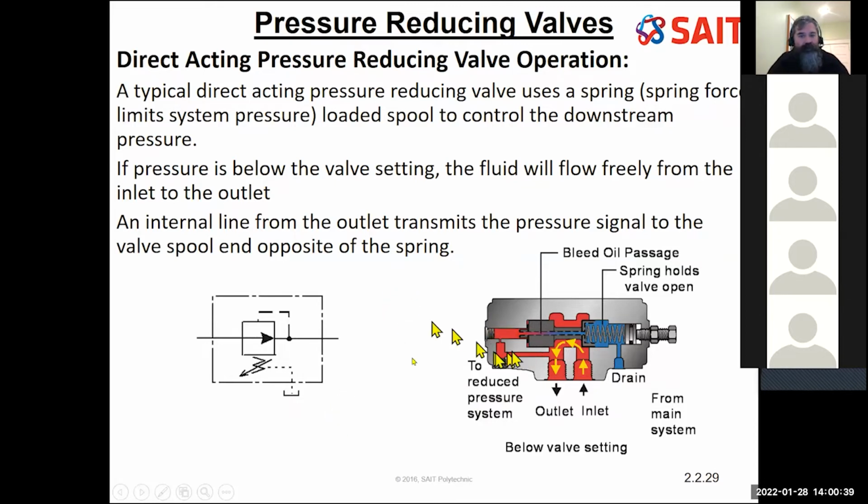So that's why we have this high pressure line operating against the surface area to move this spool backwards and forwards, and this small dotted line coming off the valve on the spring side going to drain. If I block that, I can have a pressure lock, and this valve doesn't move, it stays wide open.